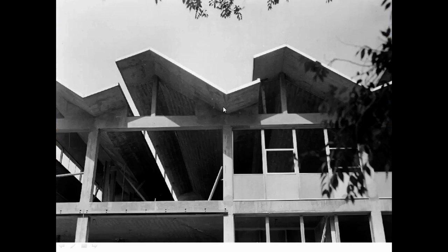This is a beam. This is, of course, probably a building from the 1960s, and the roof of this building, yes, there's some gaps here at the moment, but they will be filled. There will be glass, won't there? The roofs are great big folded concrete sections forming the beam. But again, let's understand that the span to depth ratio is from that point to that point. That's how deep the beam is. The folding of it, of course, is giving it structural stability, isn't it? So it's a fold. Any kind of folded structure will give it that, but that's the span to depth ratio. So it's a very long span right across to the other side over there.